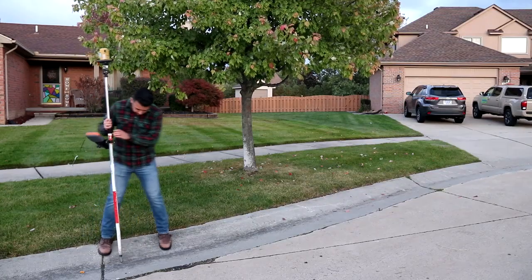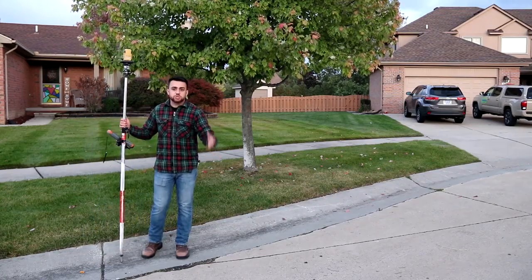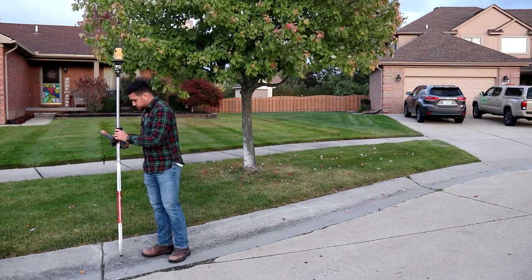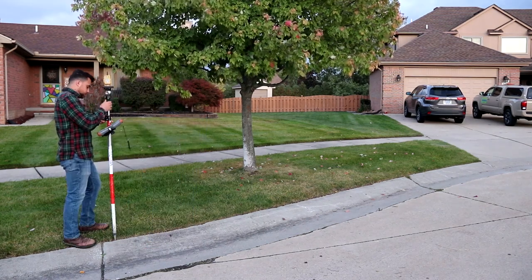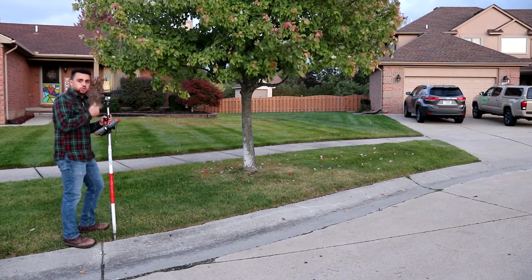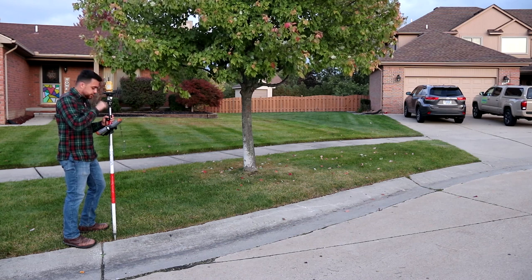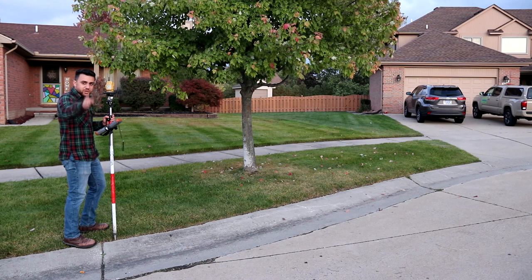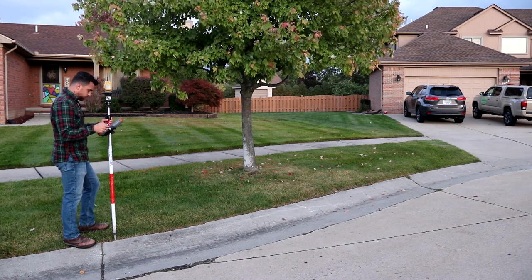Now we're at a curb and gutter again. Off camera, I'd already finished curb and gutter 1, so I can go ahead and reuse them again. Gutter 1, lower the rod here. Anytime you lower the rod, be sure to put the new rod height into your data collector so it can re-account for the elevation change. Very, very, very important. Curb 1.